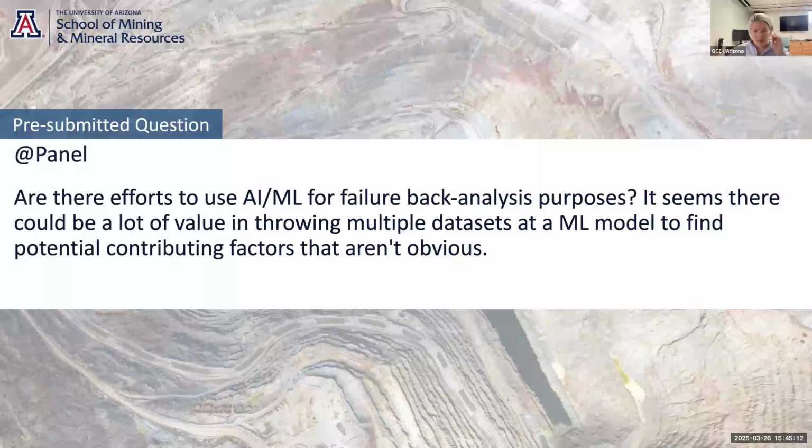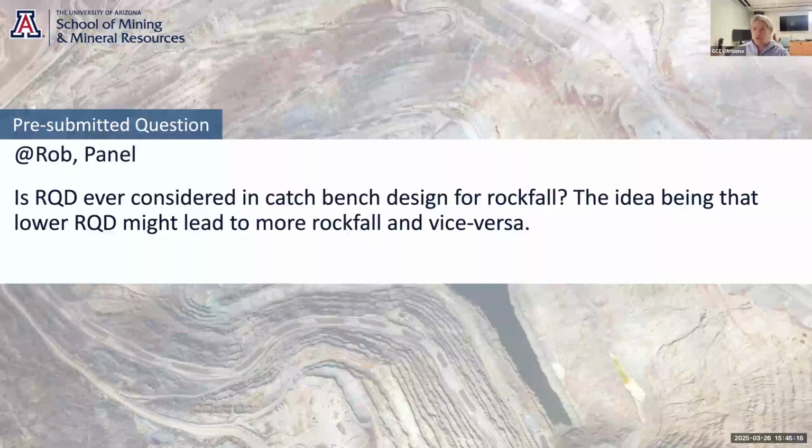All right. We'll move on to a question for Rob, and that is, is RQD ever considered in catch bench design for rockfall? The idea being that lower RQD might lead to more rockfall and vice versa.